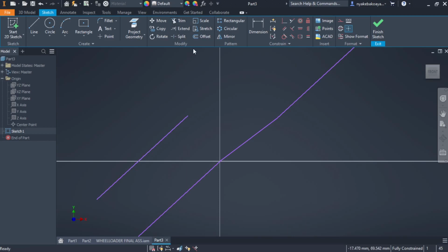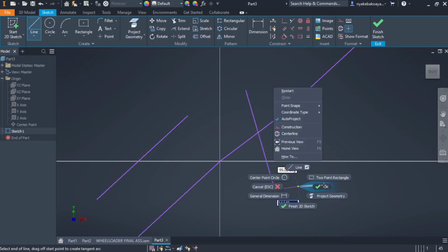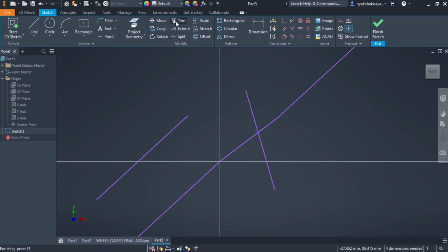And then we have the Trim tool. Let's say we had a line going there like that, click OK. The Trim cuts geometry. Select Trim there. What the Trim tool does is that it removes geometry up to another line. Like you see where they are intersecting here, it will erase all of this and leave it up to the point where they are attached. So you can trim these, you can trim that, you can even trim that. So Trim not only trims but it also deletes.